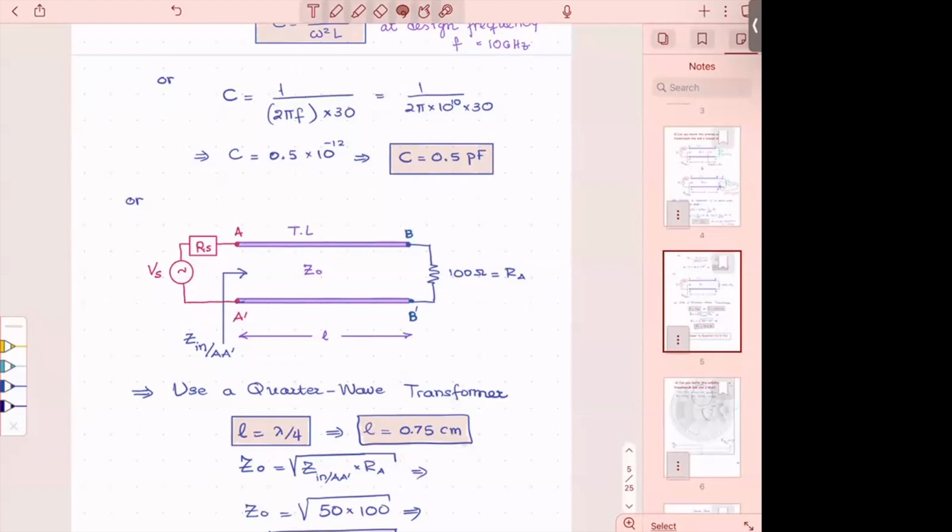So for example, my antenna may have a coaxial input, and then I need a coaxial output out of this. So where am I going to put it on the coaxial output? I can't do it, all right? So obviously you need to be somewhere inside and away from the ports, remember that. Practically, you don't put anything either at the input port or the output port. However, theoretically, it's not wrong, but practically it is.